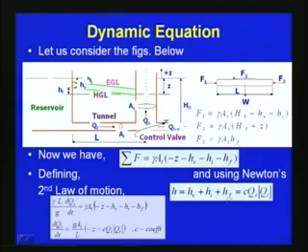Here we consider the mass as gamma L AT by G, and the acceleration we write as dV by dt, which is represented by dQt by dt, where Qt is the discharge through the tunnel. So gamma L AT by G into dQt by dt is equal to the net resultant force, gamma AT into minus Z minus HV minus HI minus HF.